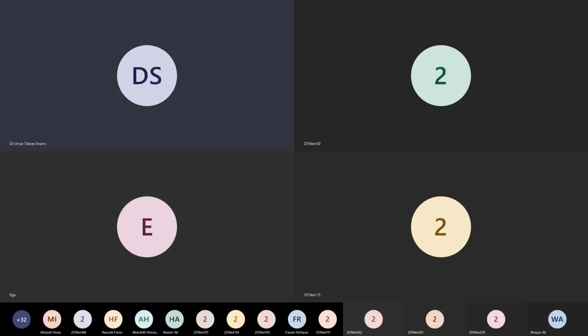You can reduce the ripple by increasing RL, which is very possible and very true, but the value of RL is defined by the load itself. If you want to connect a DC motor, the user can never control the resistance of the motor. If you make the resistance very large just to make the ripple voltage very small, the ripple voltage will become small, but the motor will not run because the motor requires current. Therefore, we have to use other techniques to reduce ripple.